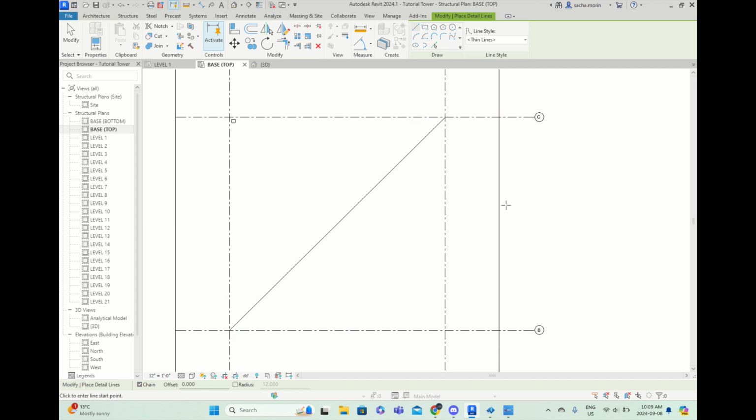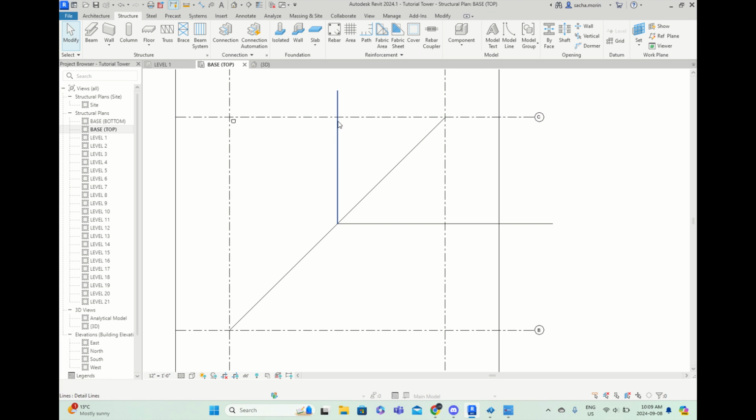And the easiest way that I have found to do that is really just a tip and trick that I found out in AutoCAD. If you make a diagonal line here, the midpoint of that line will make up your axes of symmetry. And that's quite useful for when you want to mirror stuff. So I'll draw kind of my vertical symmetry, my horizontal symmetry. And then we can use the mirror tool from there.